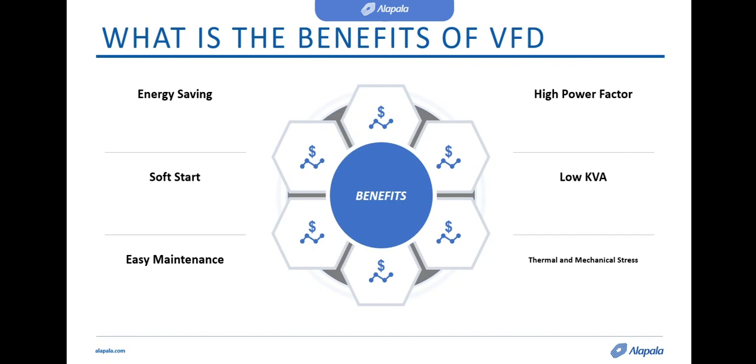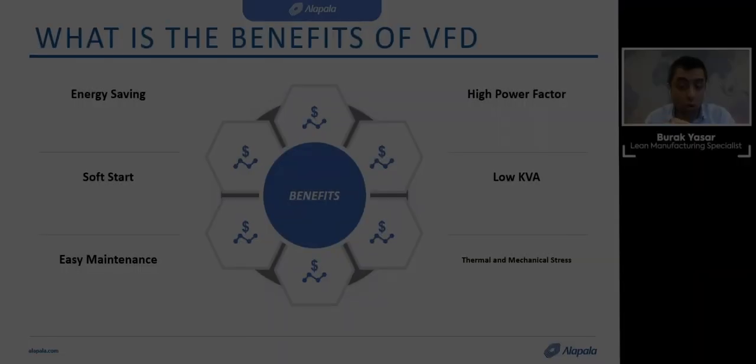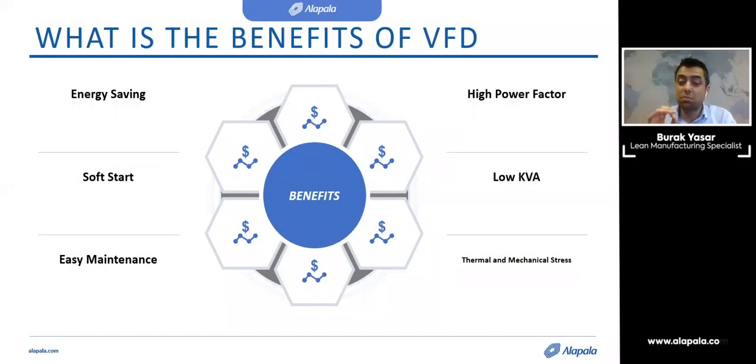Soft starts or reduced voltage soft starts are also able to step a motor up slowly, but drives can be programmed to ramp up the motor much more slowly and smoothly, and can operate the motor at less than full speed to decrease wear and tear. They can also run a motor at a specialized pattern to further minimize mechanical and electrical stress.